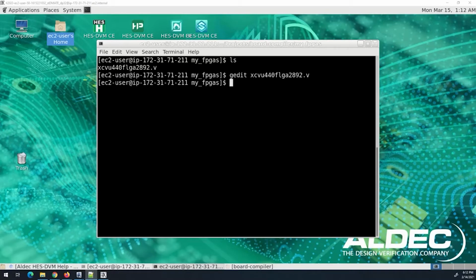Other than the FPGA chip Verilog file that shows the I/O pin assignments of the device, we need to have the custom board Verilog or SystemVerilog file, which contains the information about the interconnections between the FPGAs and also the global signals used on the board. This file is usually provided by the board supplier, or the user has to define it.